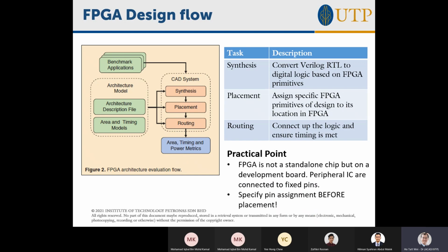Okay. And again, there are some constraints here for ASIC, for ICs, the application specific ICs. The routing is done for maybe up to 7 layers or a few set of layers, and you cannot have unlimited wires. I think you can start to see that the placement and the routing have a very close relationship. If you place gates that are connected to each other very far apart, you will soon run out of space and wires to crisscross. So gates that have to be connected together, you try to put them close together so that you can cut short the length of the wires, and there are certain